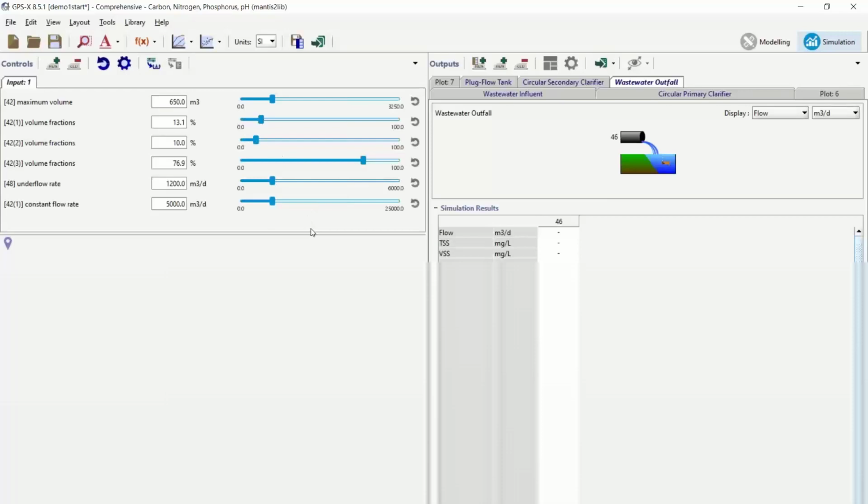And now we have our graphs that we can use to understand what's happening here. So in the system here, we can see, of course, that in that aerated zone a lot of the ammonia is coming down. It's being nitrified. There's nitrate here. And so this is an effluent ammonia, or at least at the end of the aeration tank. We're assuming there's no biology happening in the clarifier, so this is the same as the effluent. 0.36, that's not too bad. What's our ortho P? We know it's at 1 point something, 1.15. So we're going to try and adjust some of this to make it better.